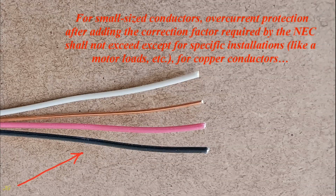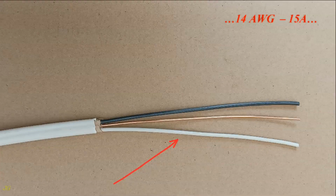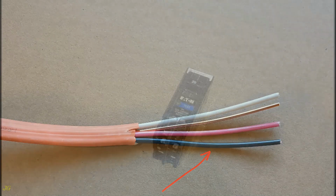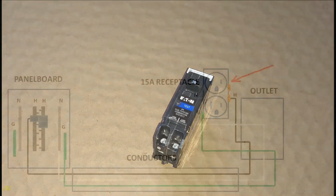For small-sized conductors, overcurrent protection, after adding the correction factors required by the NEC, shall not exceed the following, except for specific installations like motor loads. For copper conductors: 14 gauge, 15 amps; 12 gauge, 20 amps; 10 gauge, 30 amps. The overcurrent device, circuit breaker, can also provide arc fault protection and ground fault protection for personnel.